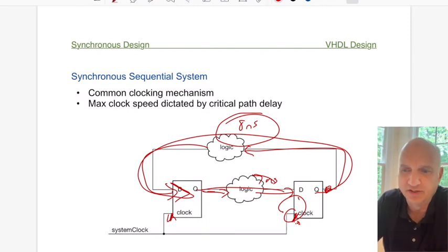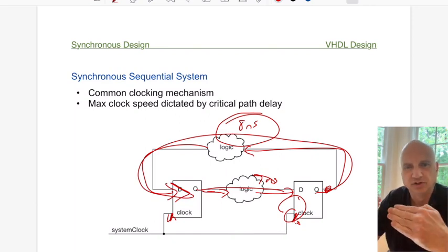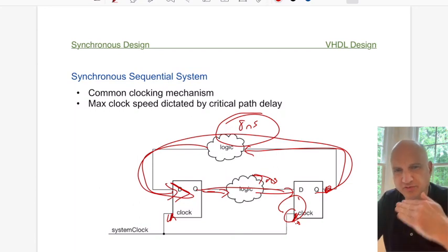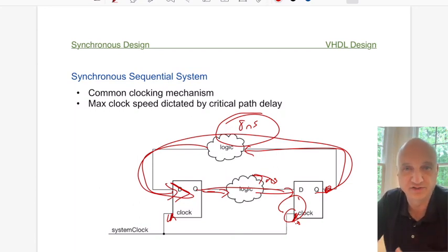They work on path delays, they look at the routing structure of all the clocks, and they balance it out to make sure that there's no skew with one clock hitting a little bit sooner than the other clock on an element, causing some real havoc in your design, right? So we don't want that to happen. So these dedicated clock paths are important for having that happen.